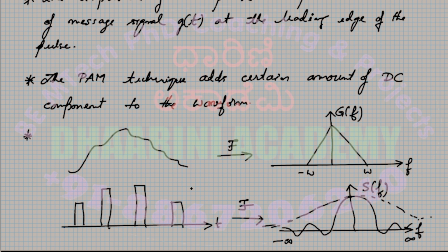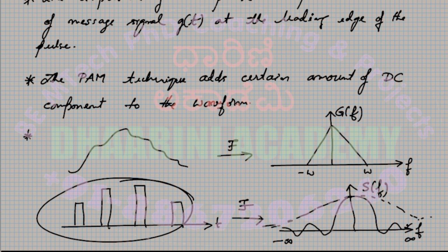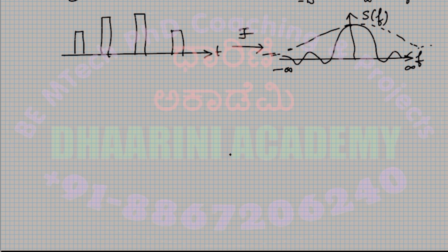So when I converted my message signal, the analog signal that you see here, into the PAM signal, the bandwidth requirement exceeds whatever you had allocated. It's a baseband signal, so we have only W hertz available for transmission, but because of the conversion of the signals into the PAM representation, we have a wider bandwidth requirement.